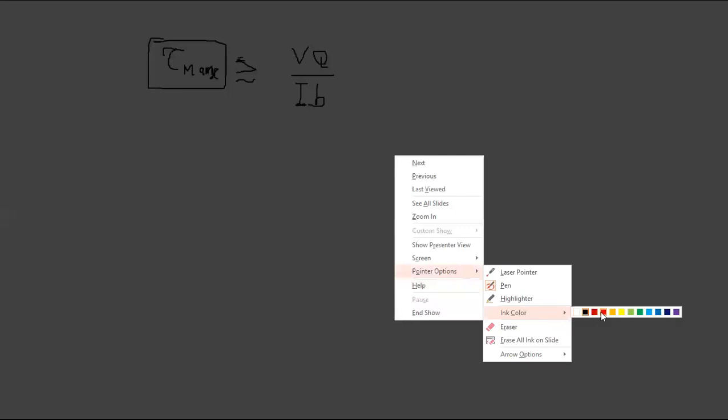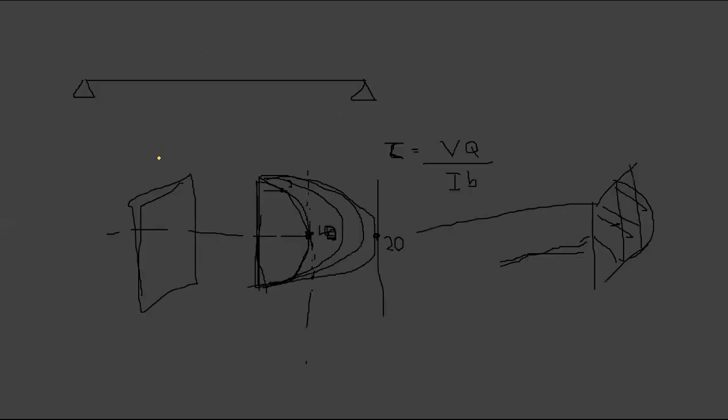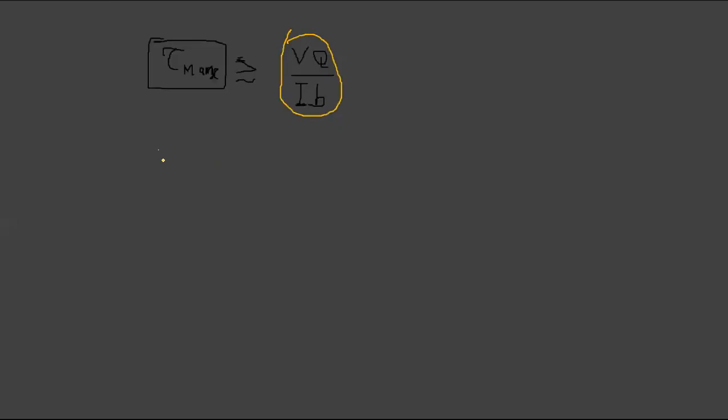This is the shear stress acting at the neutral axis. So if our resistance is larger than the available shear stress, our beam is not going to fail. But if it is less than, so larger than or equal, right? Equal means almost about to fail. So now we need to know this is 3. I think the value is, yes, 3 megapascal means 3 newtons per millimeter square, right?